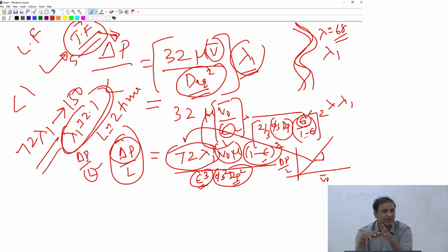However, for the sake of simplicity, we assume straight channels. We said there are n channels of exactly the same length as the packed bed, and we did a very simple volume balance and surface area balance. That gave us a way of estimating the equivalent diameter of the conduits through which the fluid is flowing.